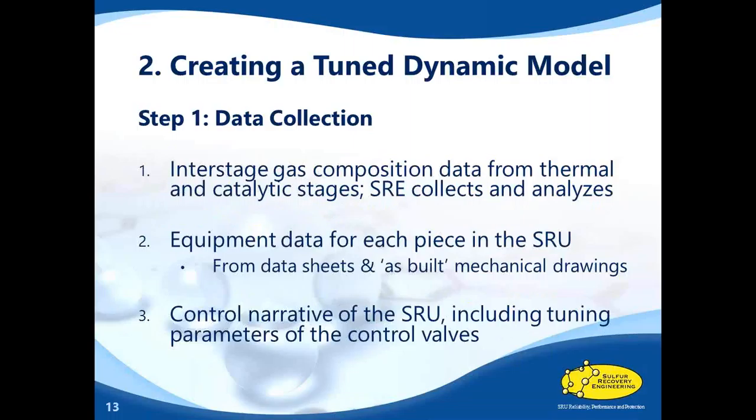And that's the first step in getting this tuned dynamic model, to understand and collect accurate results for each process gas stream throughout the SRU. Also, we want to collect a good pressure profile of the SRU as necessary. Next thing is the data mining exercise.